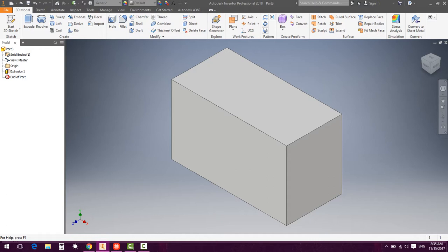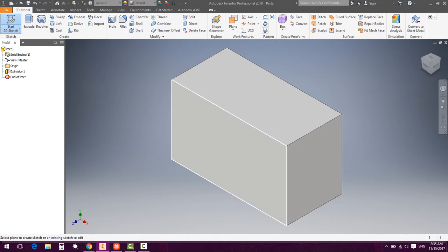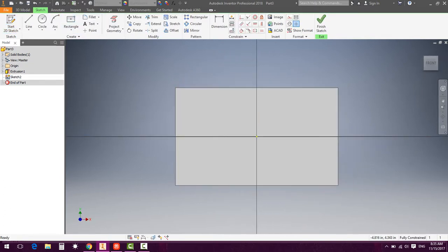Now I need to add my cylinder onto the front of my 3D angle block. So I'm going to click Start a new sketch, click on this first front, and since I know the cylinder is up in this quadrant, I want to go ahead and draw it over in that area so that I don't have to move it as much. I'm going to click one time, and again, when that blue number is highlighted, I don't have to drag this and get perfectly to 5. I can simply enter 5 on my keyboard, hit enter, and my circle is done. I need to shut the circle feature off, so I'm going to right click and hit OK.